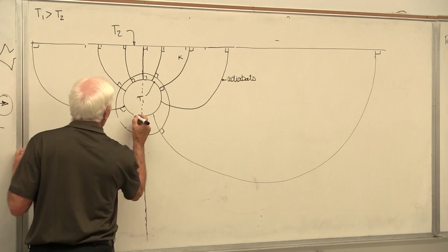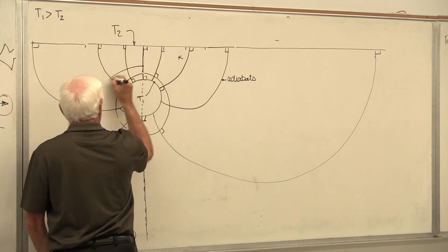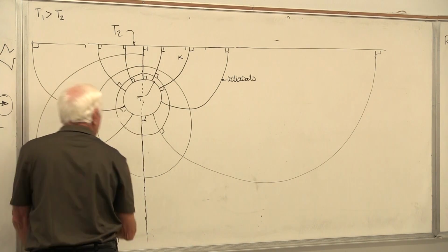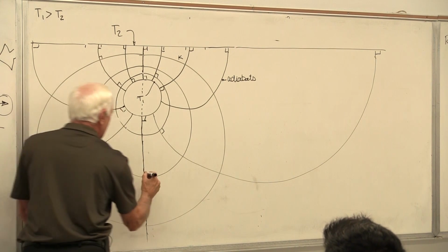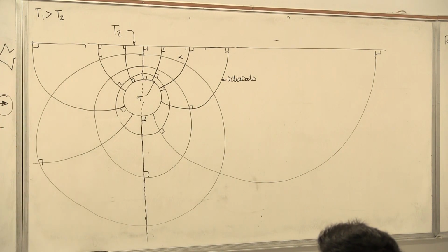Okay. So here we go again. All right, that's one. Let's draw another one. And another one. Notice everywhere, these guys cross at right angles, or they should cross at right angles. They're not a bunch of concentric circles, no. They're all crammed up near the top, and they spread out at the bottom. Now that is how you draw a heat flux plot.